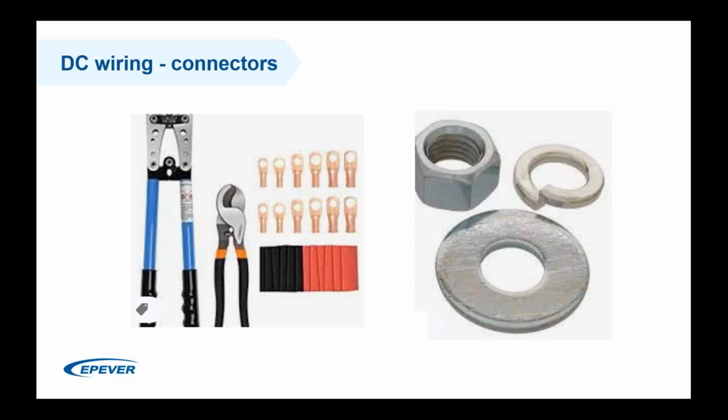Again, special care is required when connecting the locks to the mounting surface. This is also important. There should not be anything between the lock and the surface. So if you have, for example, a copper bus bar, your lock should just perfectly align to the surface of your copper bus bar. Well, you can put over it the washers and the spring ring and the nut to tighten it, but there should be nothing between the lock itself and the copper surface.